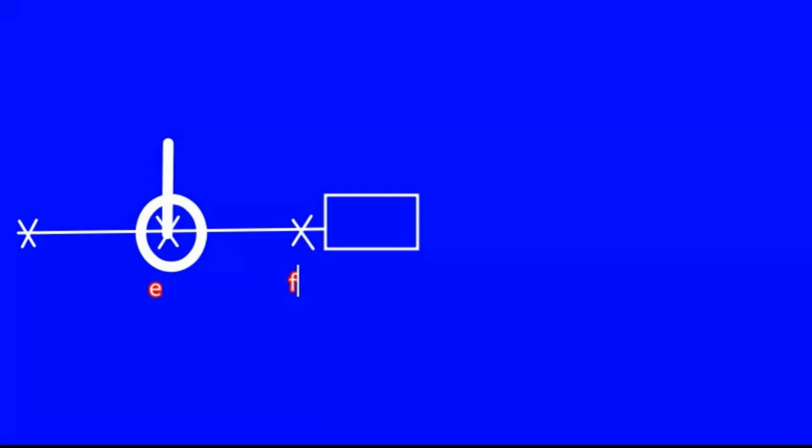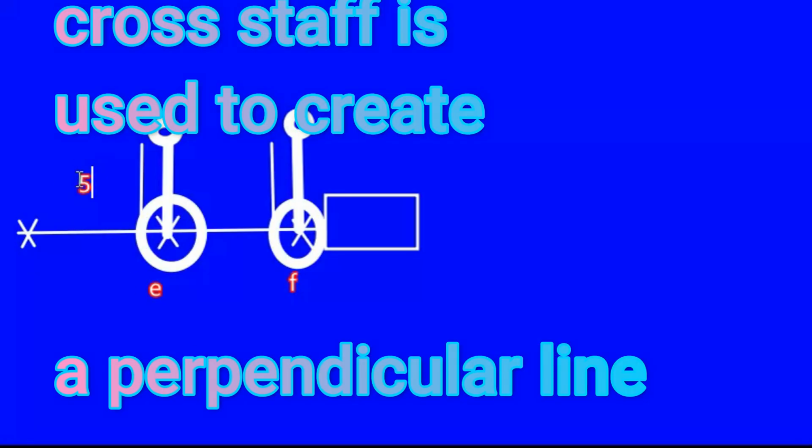So over here I will now again place the cross staff placed again at this location, and with the help of that we will put another ranging rod somewhere around here, and we will make sure that the distance is equal. So you can measure this distance over here from here, right? So we'll measure this distance, say this is 5 meters, then this should be also 5 meters. Both of them should be 5 meters each.